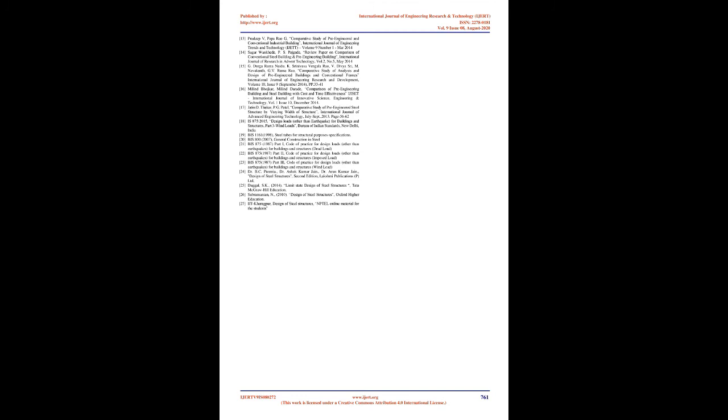2. The weight of steel, in kg, of web-tapered portal frames is less, by 15.38%, than of conventional steel buildings. 3. The weight of steel, in kg, for column of web-tapered portal frames is more, by 15.22%, than of conventional steel buildings. 4. The weight of steel, in kg, for rafter, vertical and inclined members of web-tapered portal frames is more, by 15.22%, than of conventional steel buildings. 5. The total weight of steel, in kg, of web-tapered portal frames is less, by 28.21%, than of conventional steel buildings. 6. The total reactions in kN of web-tapered portal frames is less, by 15.076%, than of conventional steel buildings.